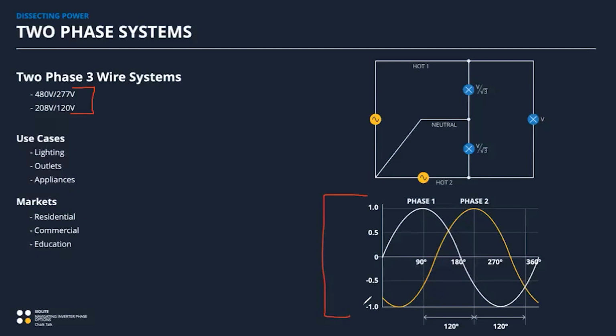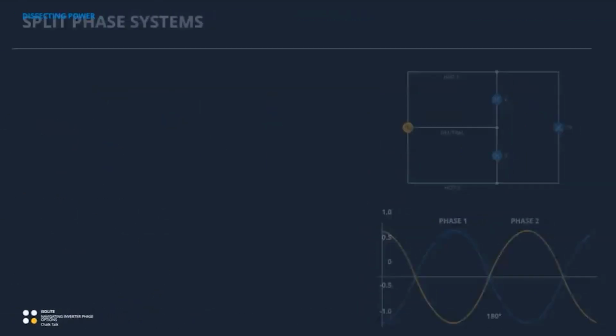Again, it's pretty rare. There's a little bit of wiring nuance about how you deal with this and when isolation transformers are required. Generally speaking, 2-phase is the least common of the options that we offer in our large inverters. So if you do see it, maybe take a quick look and just make sure that you're just driving loads, you're not trying to feed a sub panel, and that it's really just done to sort of match and balance loads off of each of the phases of a 3-phase system upstream of it.